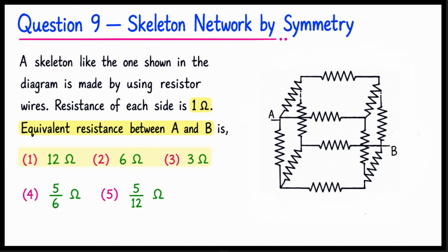Without the symmetry trick, this would mean solving a 4-resistor square problem by writing out loop and node equations. With the trick, it is 3 visual steps followed by a single line of arithmetic. The punchline is that the answer 5/6 of an ohm comes from welding together points that are at the same potential by symmetry, then collapsing the resulting series chain.